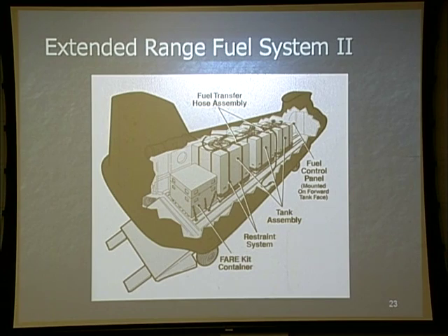Okay? And it's quick. With the IRFs 2, it refuels just like the aircraft does. It'll automatically shut off. It operates off of a bladder system with a Kevlar internal tank. In other words, it's not only crash-worthy, it's ballistic protected. And it operates just like the aircraft tanks do. Instead of carrying 3 600-gallon pods, these are 800-gallon pods apiece, and we can only carry 3 of them. And you'll notice there's a lot more information on IRFs 2 in your Dash 10 because they are a crash-worthy system.